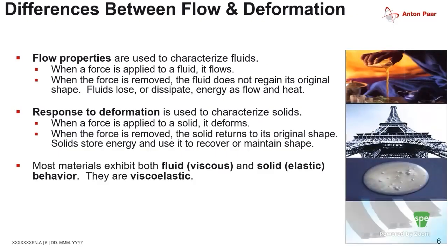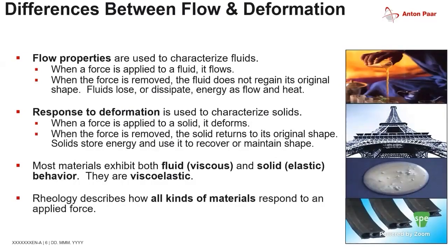Now, for the most part, most materials are not an ideal liquid like oils, or an ideal solid like steel or stone. They're a combination of the two, which is what we call viscoelastic materials. They have both fluid-like responses and solid or elastic behavior. They may behave like a fluid but still have some ability to retain shape, like a shampoo, which is a viscoelastic fluid, or a sealant, which is a viscoelastic solid. Rheology allows us to describe the material through any of these types of responses.